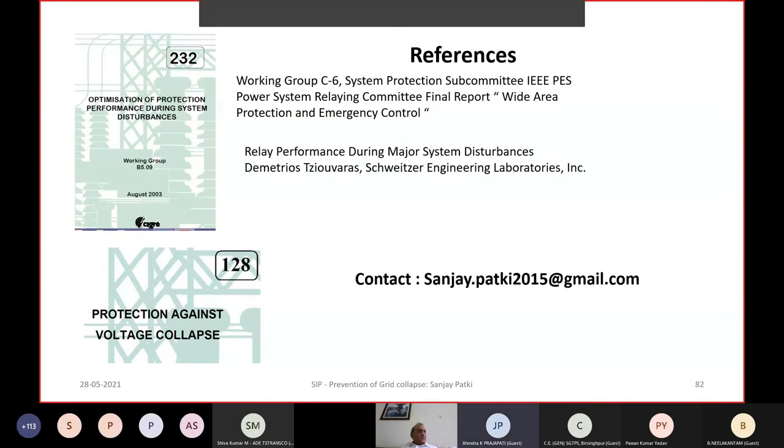But sometimes it comes at the same distance also, sir. Actually, around 50% of the line length, it comes around the correct distance, and at more than 70-80% it goes to a very different reading. So is there any lumped element calculation or something special that should be taken care of for that?